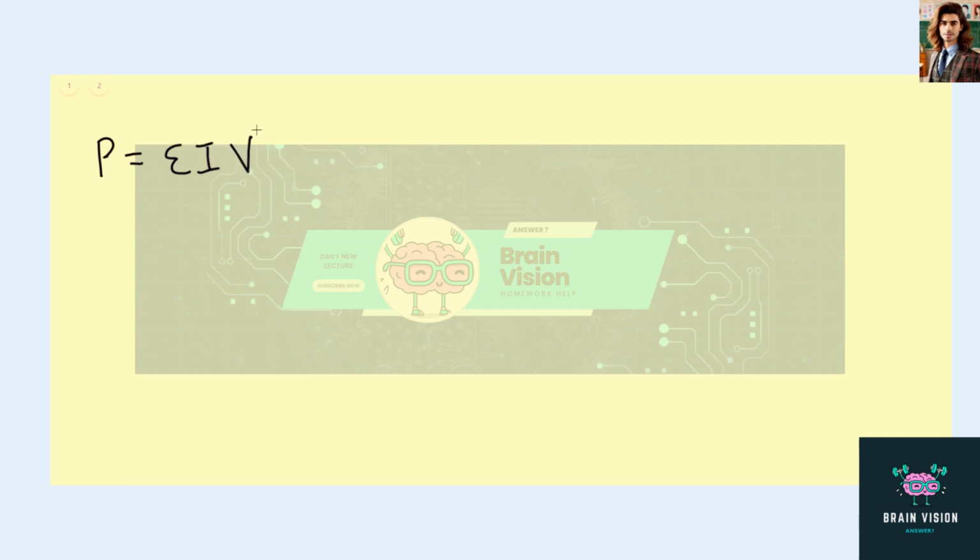So finding the power being delivered to the X-rays is relatively straightforward. With V of 18 kilovolts, so 18e3, we end up with 10.8 joules per second, also known as watts. So that's a really simple result for the first part.